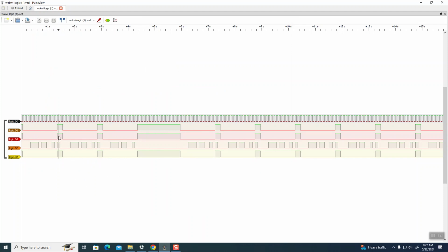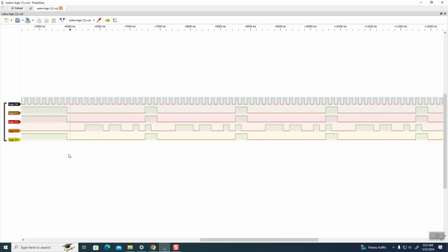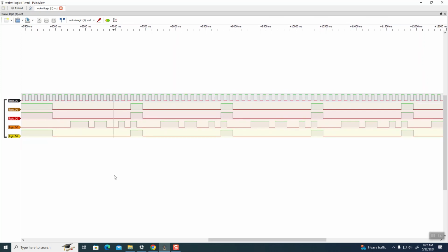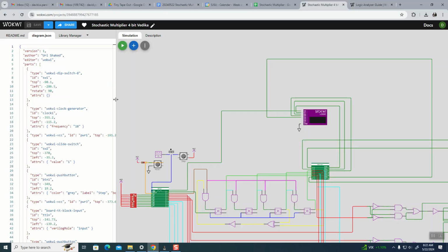So this was what was going on before. This is me hitting reset. Right, I can just zoom in, and in this case, this is the stream. When I'm having 0, right, this will be 16 clock cycles, and then it'll go high for 1 clock cycle, and then high for another clock cycle, which might be unexpected. And yeah, I'm trying to encode a 1.